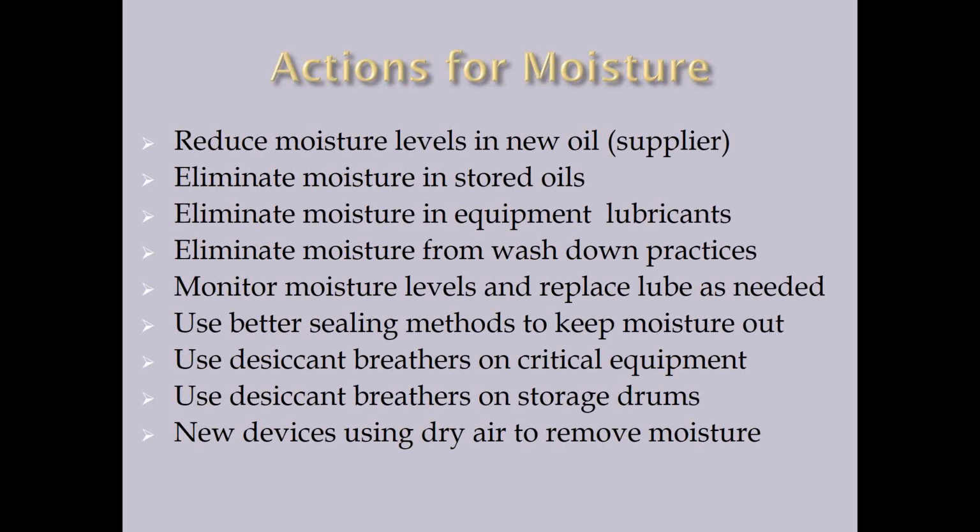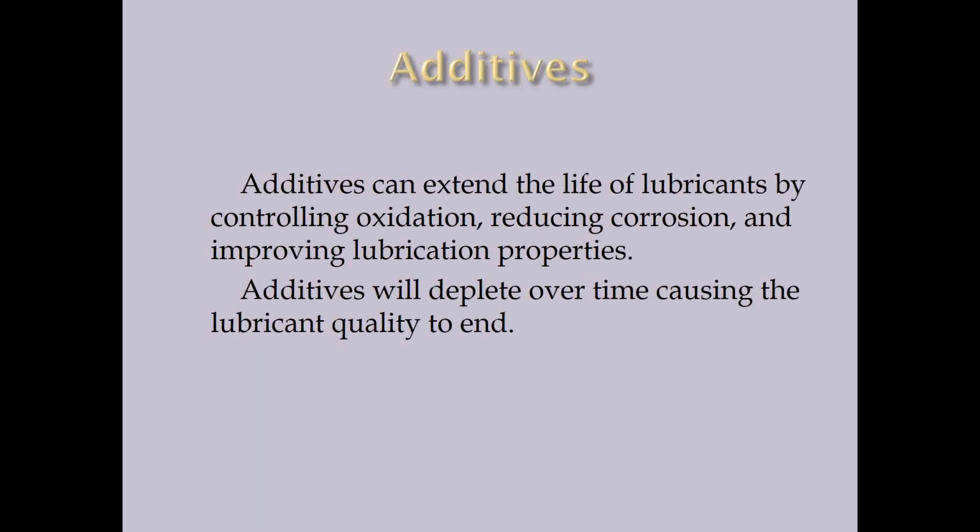Desiccant breathers on your storage drums. A lot of places I go, the desiccant breather on a storage drum will last over a year because the drum's not breathing that much. But again, it depends on where they're stored and how well you store them. Then these new devices, the dry air to remove moisture, using nitrogen to remove moisture. All things we'll cover in the next training session. But moisture, big issue for the life of your equipment.